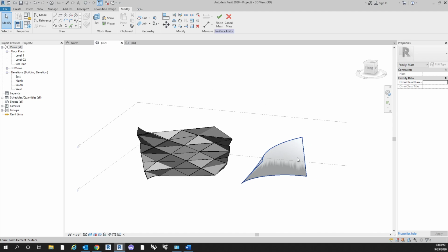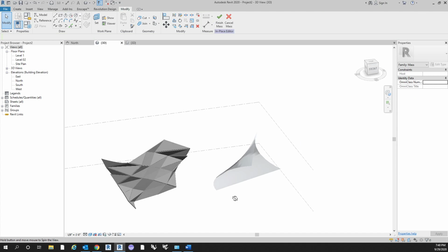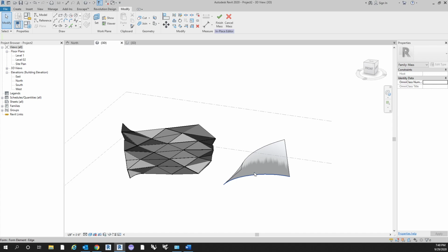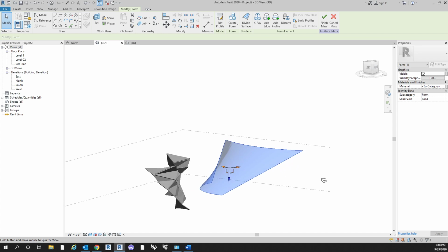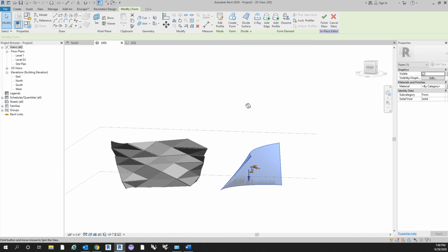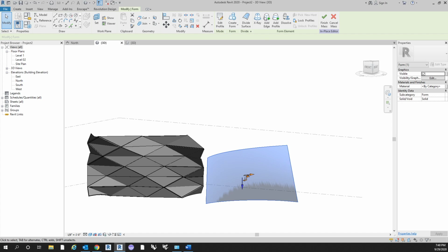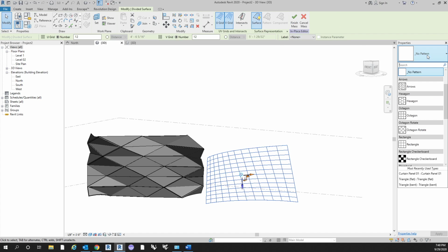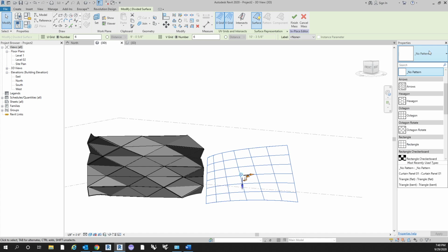Now, you may find, when we start getting into Rhino inside and start to do some more scripting, we'll have a lot more control and we can explore curtain divisions. But for right now, we are limited to what we can do within the Revit toolbox. So select the surface, divide surface. Let's first change this to a smaller division count, 6 and 6. U and V grid is basically just the X and Y that follows the surface